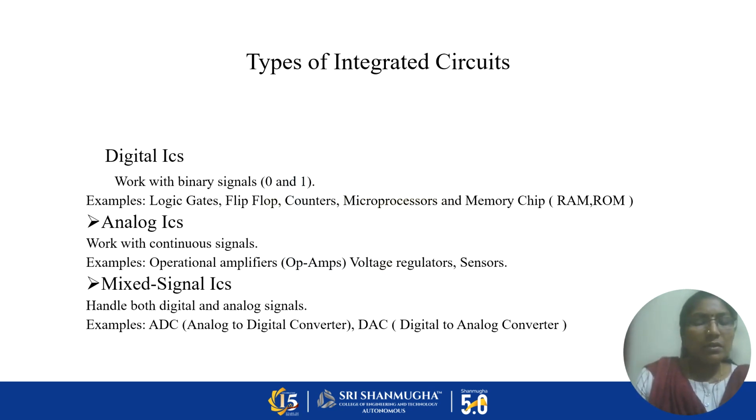A combinational circuit has no memory unit, and its result is based on the present input only. For example, adder, subtractor, multiplexer, demultiplexer, encoder, decoder, parity generator, checker, and magnitude comparator, etc. Since the combinational circuit has no memory unit, the results are not stored in this system.